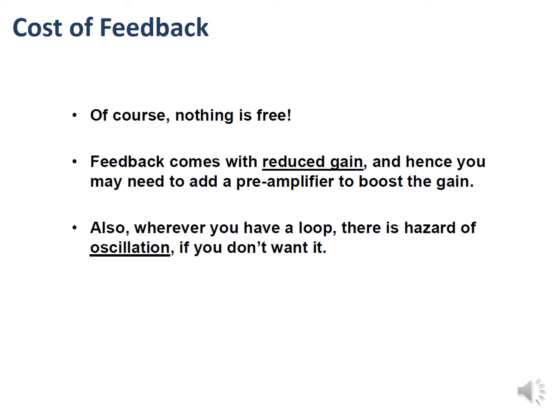If that feedback has reduced the gain too far, then we might have to go to a two-stage design, where we have a preamplifier to boost the gain before coming into a power amplifier. So we need to understand that negative feedback is really useful in amplifier circuits, but this reduction of the gain is a major downside. And of course, if we did generate positive feedback in some way, then we're going to end up with oscillation, which we want to avoid in most cases.